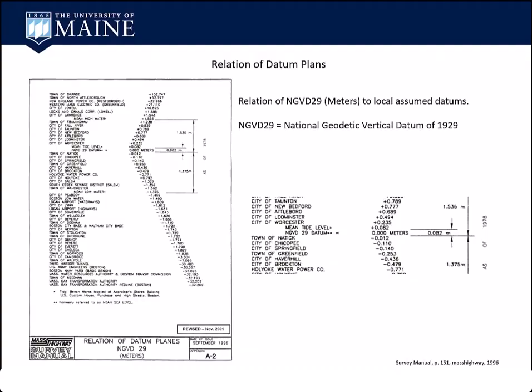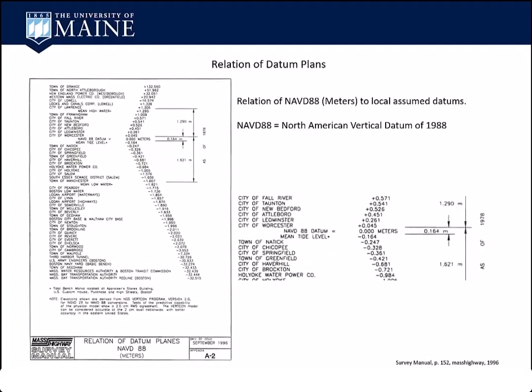So they just assume datums are fine, and they just stayed on these systems, especially anybody that has below ground works. But if you're working in those towns, you would go to the town and get control to be on that datum. And then you would list it in the field book, like we saw earlier. This is 88, related to all of the different assumed datums.